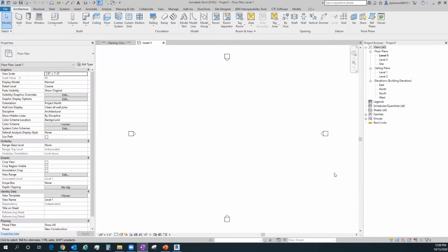Usually it becomes a little bit harder to figure that out. Maybe you got a whole bunch of model updates from more than one vendor, you place them all in the right file folder and replace the old files, and then suddenly something blows up and you don't really know which one may have caused the problem. Or if you're working inside Revit and something crashes and you're not necessarily sure what happened, but maybe you got a warning message that popped up right as you crashed. It says, Revit can't continue. Do you want to save a backup file? Things like that sometimes happen. Other times they just blow up and die, with no warning whatsoever.